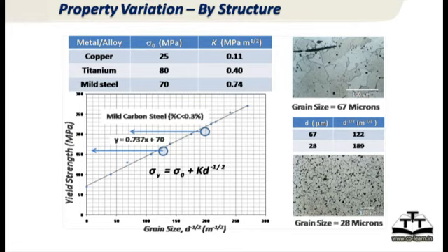Okay. Now, there are already good relationships between structure and properties. So if you know the structure, you can predict the properties, especially your hardness and strength. And relationships exist to predict that. For example, here looking at the grain size, different grain size, and from that you have the root over D, and from D if you plot, you can get the yield strength. So it's possible to compute the yield strength of various metals once you know the grain size and composition.